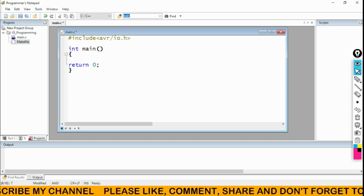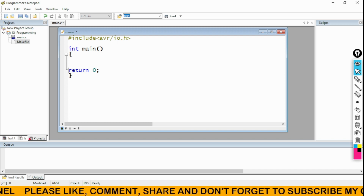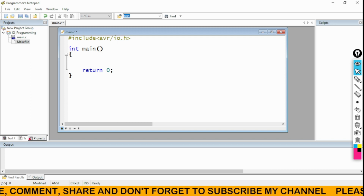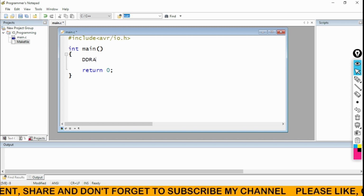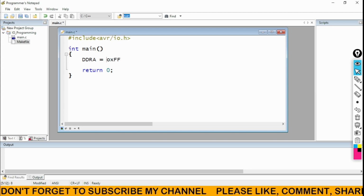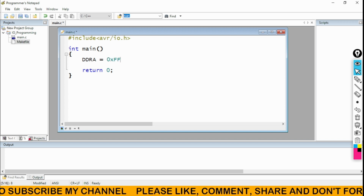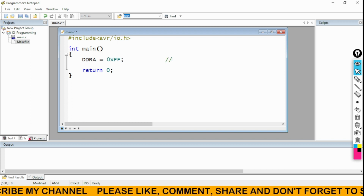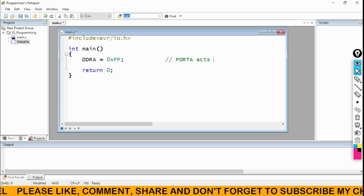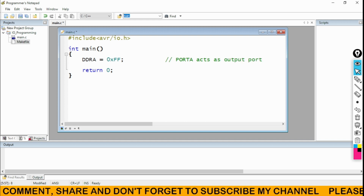return 0 for int. Now if we have to program the IO port, we need to understand that there is a register called DDRA. Suppose we write DDRA equal to 0x, keep in mind it is zero, not O, then a semicolon, which is a statement terminator as in C. Here I am writing that port A acts as output by writing DDRA.